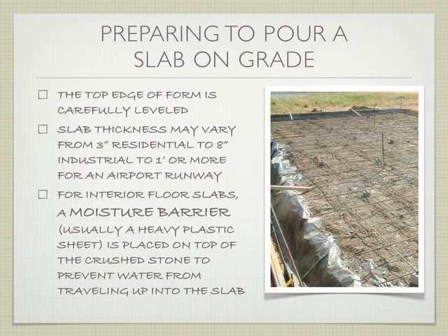And what that does is it will protect that moisture barrier from getting little tears in it, right? Because if you put the moisture barrier down and then it gets all cut up, it's not doing its job. You need that moisture barrier to be a nice continuous sheet. So if I'm out here working on this surface, tying off the steel, putting the little dobies in, the chairs to hold this up, putting my plumbing in, whatever it is, I'm not going to end up accidentally cutting this. And in that example that I shared about Rossmore, that's what had happened. There were a few cuts and nicks that had happened in that layer, and that was allowing the water to come up through the floor. So it can be a big deal, and certainly something you want to think about carefully, right?